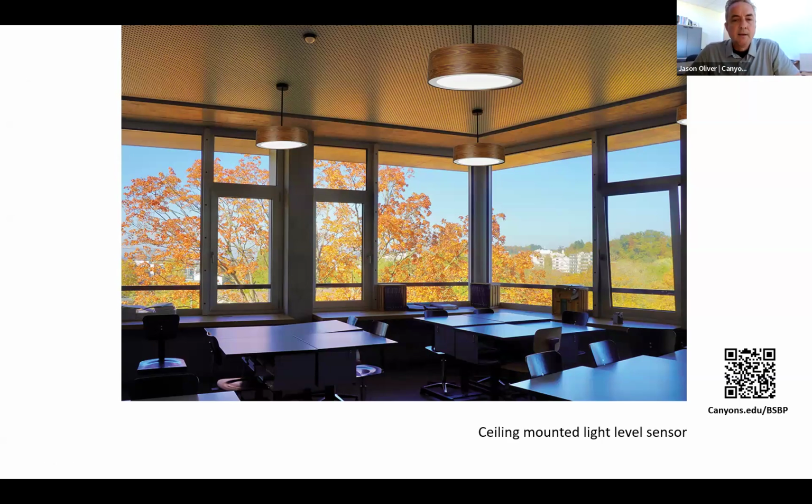Maybe we need shading. And interestingly enough, as we've been doing with our students in the classroom, we actually place virtual sensors in the spaces in the same way we would have a light sensor in a room to detect the lighting levels, so they can actually dim the light so that we're not over-lighting a space. And so we do that in the virtual model in the same way we'll do that in the real space, so that we can predict the energy consumption of lighting for that space.